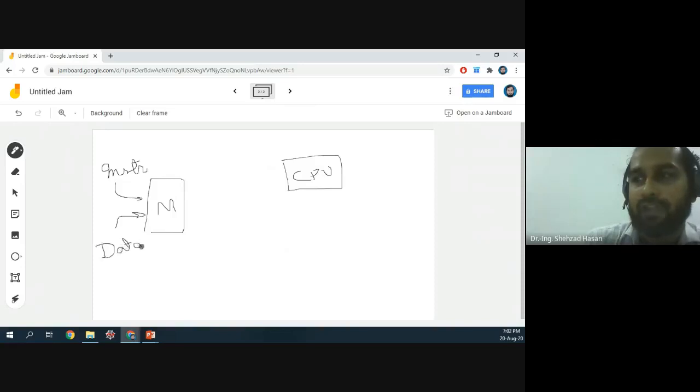For example, if I have add R1, R2, R3, that is an instruction written somewhere over here, but the data for R1 and R2, if it's coming from memory, has to come from some part over here and be stored in some register, and I'm going to work on that data. So instruction is the code, and data are the elements on which you are working.